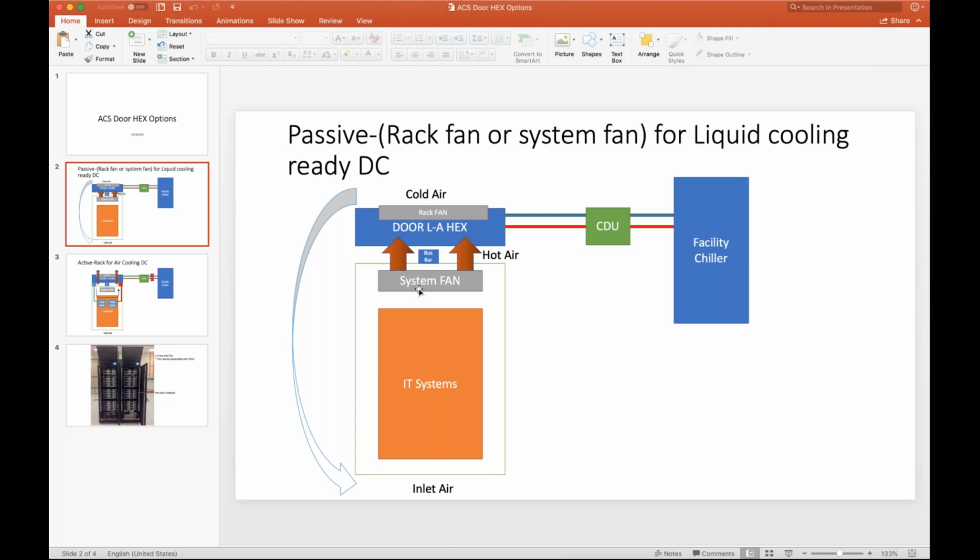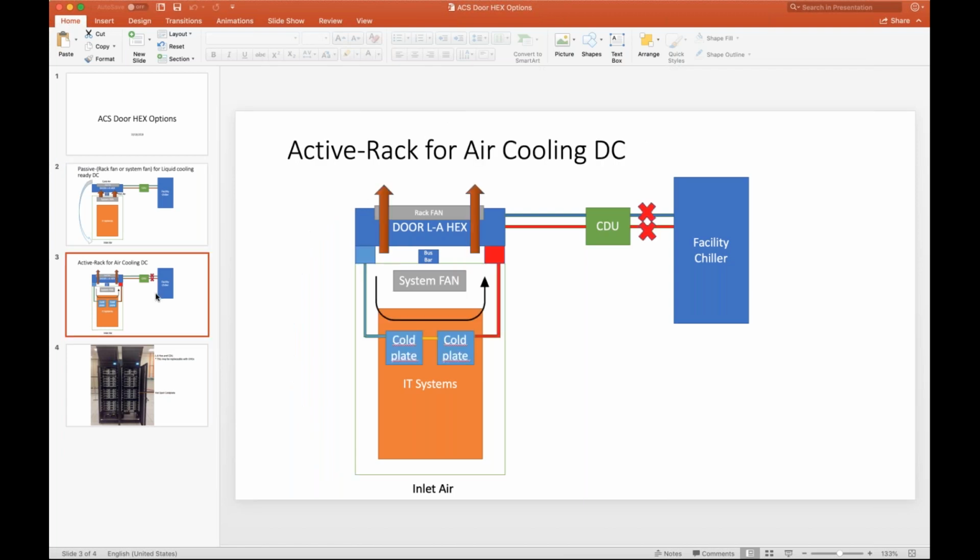Sorry, this is Jason from CoolIT. When we are operating with rear doors, we have both passive and active from a few of our partners. The passives are essentially just a coil that the server fans are blowing across, and the data center is pulling air from, whereas active would have fans mounted directly to the rear door. That's really the main definition difference to us. Awesome. So I guess the question is, what is a good way to call this type of concept?